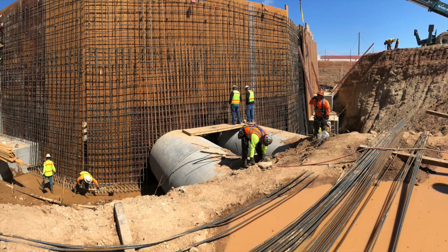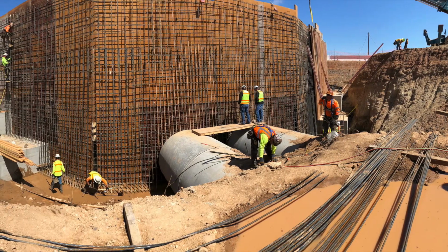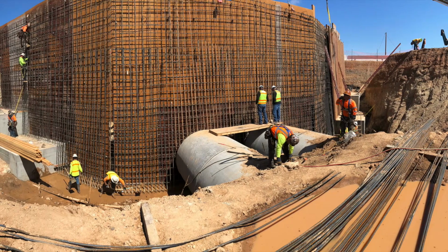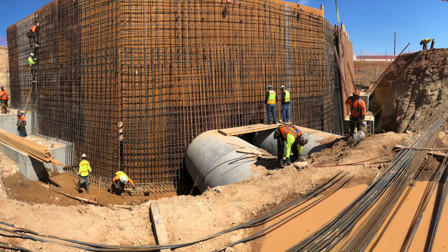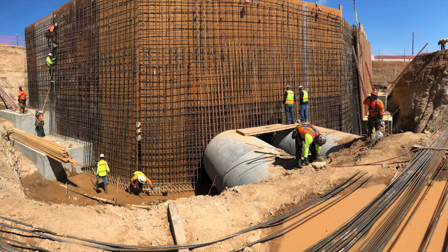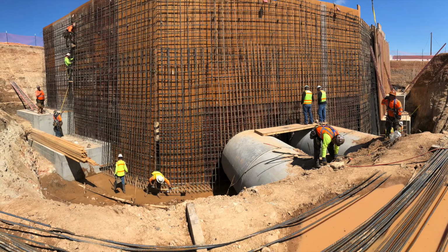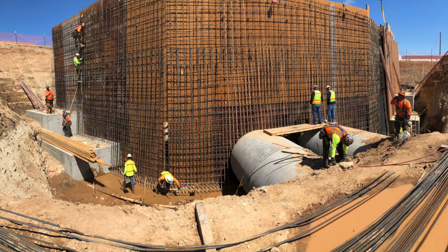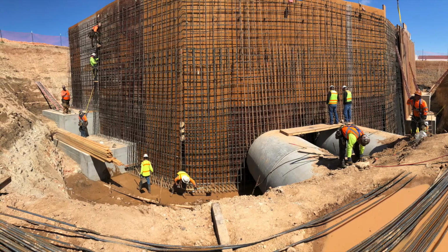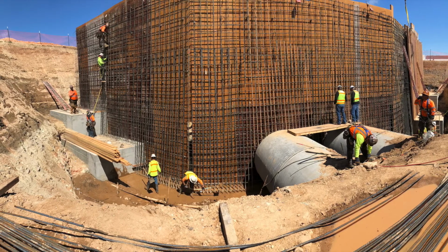Now finally, we're going to go over just a few pictures and clips I've got. This first picture you're seeing on your screen is an inlet structure. You can see the two pipes coming in the center of what appears to be a future wall. Basically, this massive wall has a rebar cage. You can see the formwork up on the far side, but they're building this cage, and then they're going to put formwork up on the other side and place an entire concrete wall, and then once it cures, they're going to strip it of its forms. And I'll show you what that looks like coming up.